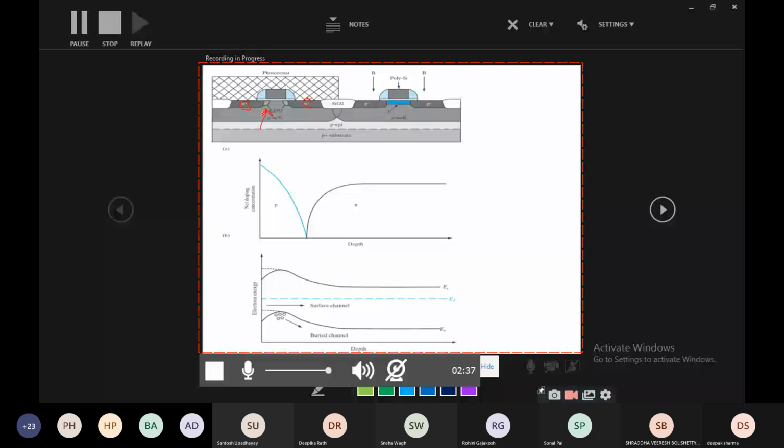To protect the internal structure from hot electron effect. And here, in N well, we have P MOSFET, right? So what they are trying to show here is that the LDD is optional for us. Wherever there is a chance of hot electron effect, yes, we can go with the LDD. And for LDD, we need to invest more because this is an additional procedure, correct? So there is no need to spend extra everywhere for that LDD.